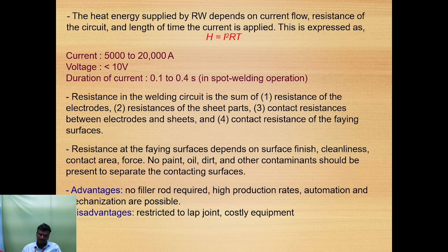The resistance welding circuit resistance is the sum of the resistance of the electrodes, the resistance of the work parts, the contact resistance between the electrodes and sheets, and the contact resistance of the faying surface. Resistance at the faying surface depends on surface finish, cleanness, contact area and force. No paint, oil, dirt or other contaminants should be present to separate the contacting surfaces.